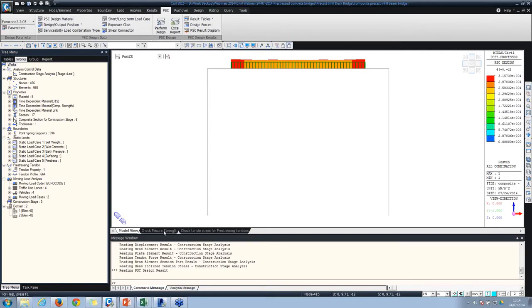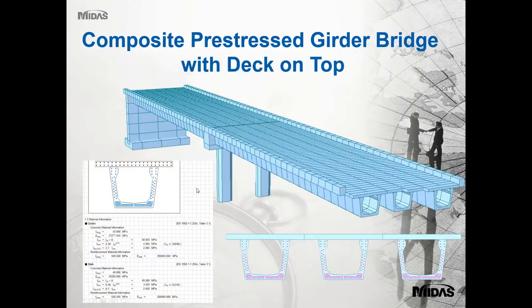Okay, so just quickly moving on to the next example, which is the W beams with slab on top. Okay, the method of modeling is a two-span integral bridge. Method of modeling is similar to what we saw for the single-span integral bridge. Here also the pre-stressed concrete girders will be first simply supported on the abutments and the pier, central pier, and then when the slab is poured, it becomes all composite and integral.